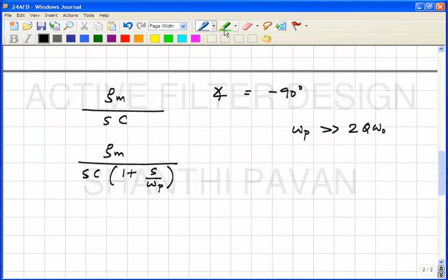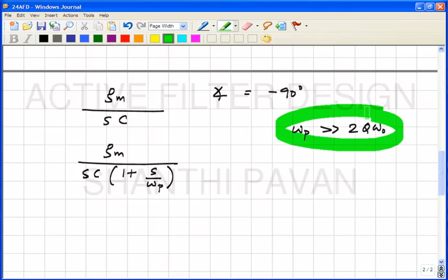Now let's see if we can understand this criterion which we derived in a different manner from the behavior of the integrator. Obviously the Gm having an extra pole must be doing something bad to the integrator, correct? So that when you put multiple integrators in a loop, the loop tends to become unstable.